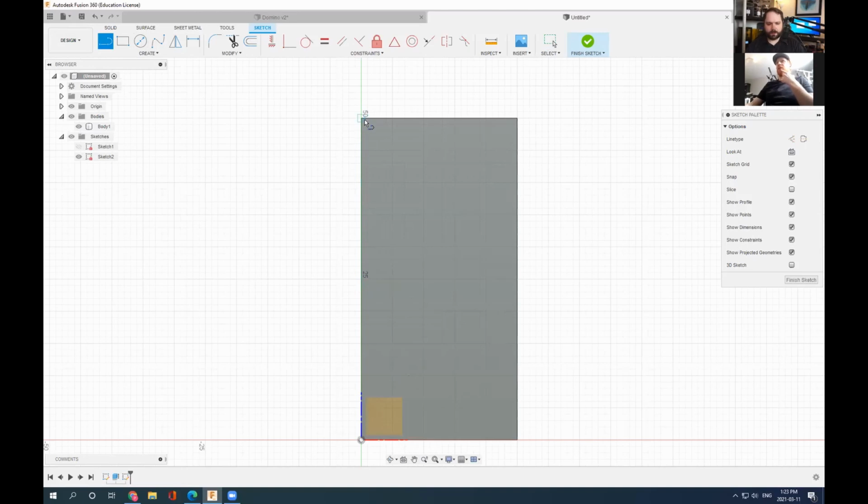And there's this really handy feature that you might notice as I'm drawing along this line. It tells me exactly where the center of the line is. So even over up here, and we're going to want to draw from the center to the center of this object, actually. Forgive me, I have zoom in the way. So I'm just going to move it a little bit. So I want to start clicking. I've selected the line tool up here. I'm going to click when I see that little triangle, and you guys are going to do that too. I'm going to click there and drag across until we get to the other side.